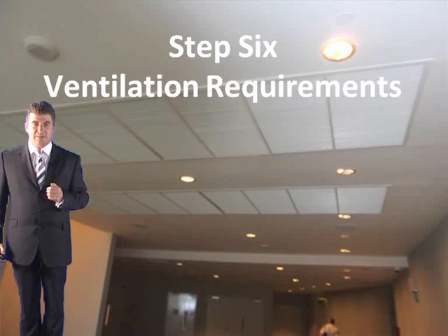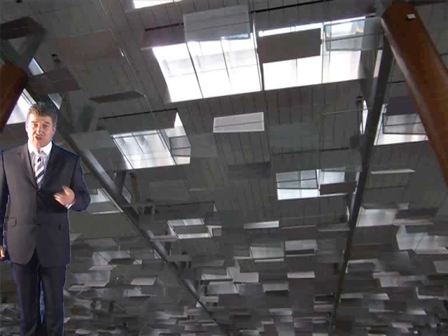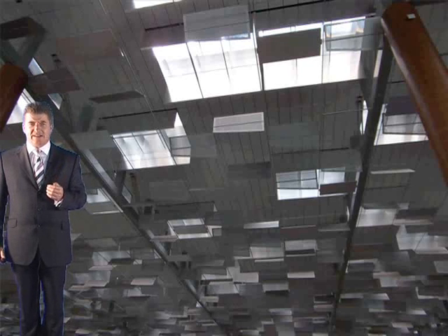Step 6. Now you've got a couple of choices here. You can go for natural or mechanical ventilation. Generally natural ventilation is preferred mainly due to cost implications, and that is obviously if it's possible. And in this situation clearly it will be the initial option. Let's progress on the assumption that we're going to do natural ventilation.